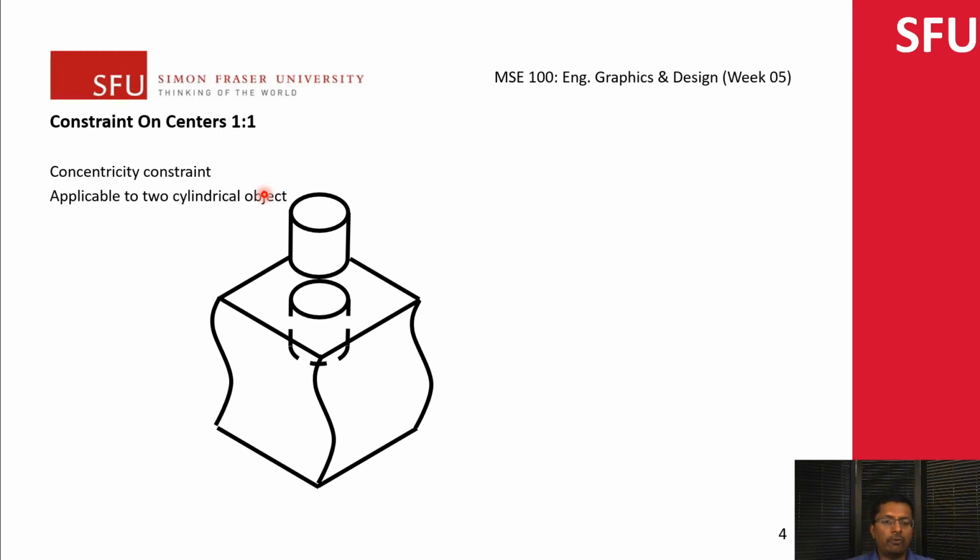For instance, if you have an engine block that you might make, then you have the cylinder. You would want to make sure, at least in your assembly, that the cylinder is concentric with the engine block. That's where we would use the cylindricity constraint. So let's take a look at this. We'll switch back to our SolidWorks over here. So here we go.